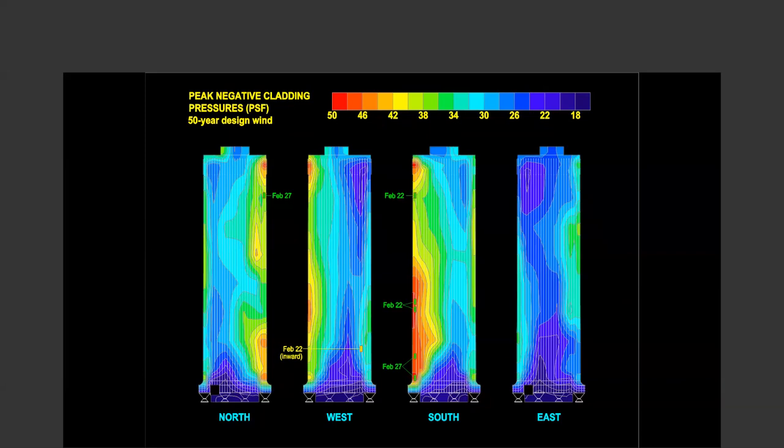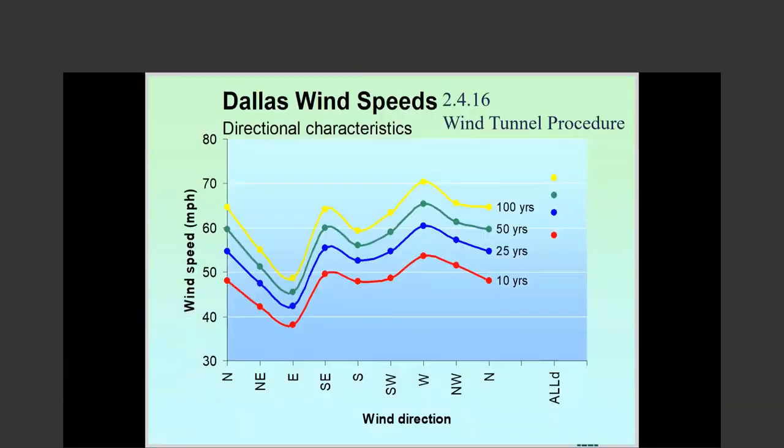The best way to get that is through wind tunnel testing. And it is used pretty widely for that purpose. Even though the structure may be regular, and you don't particularly need wind tunnel testing for the design of the structure, considering the cladding and the importance of having the cladding connected to the structure in a severe wind event, wind tunnel testing is done just to figure out the cladding pressure. So that is not at all uncommon.